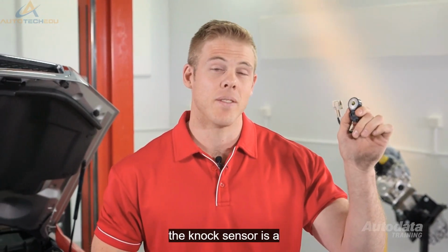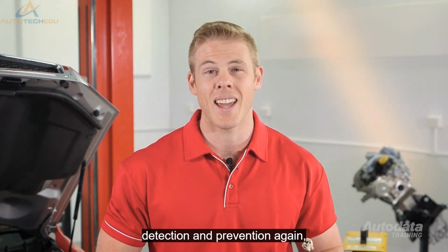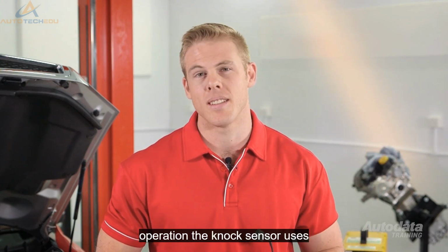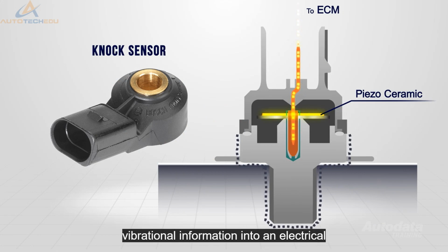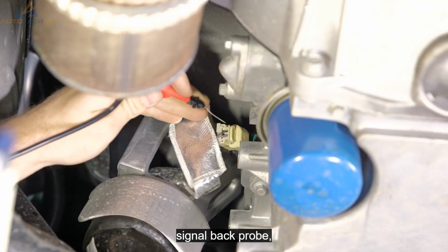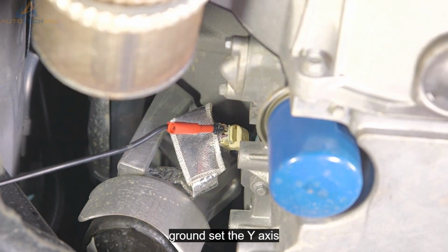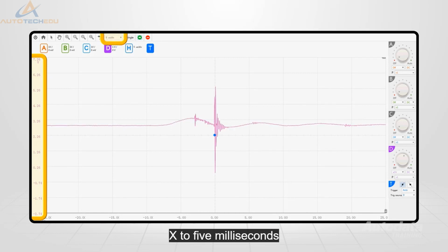The knock sensor is a vital component for pre-detonation detection and prevention. Again, this isn't a pressure sensor, but is similar in operation. The knock sensor uses a piezo element that converts vibrational information into an electrical signal. Back probe the sample lead at the sensor signal circuit and attach the other lead to ground. Set the Y-axis to 2 volts and the X to 5 milliseconds.